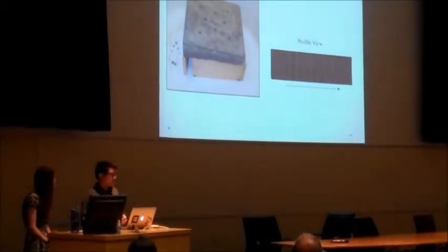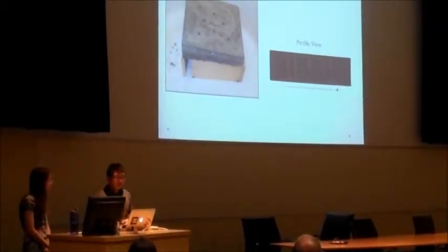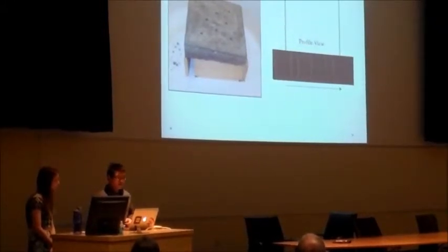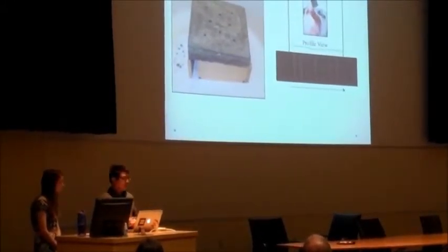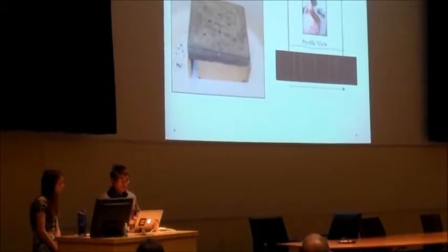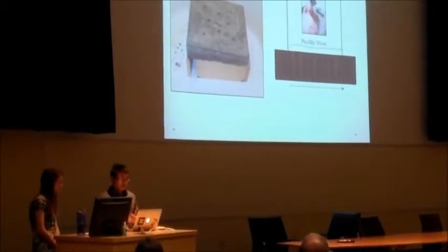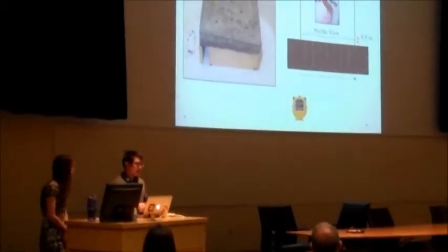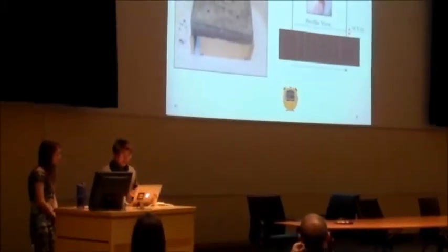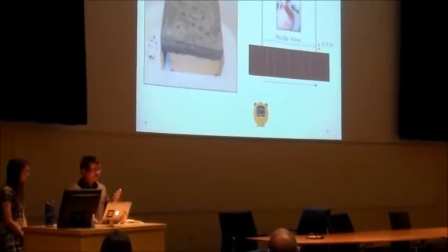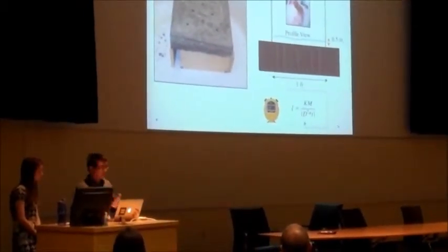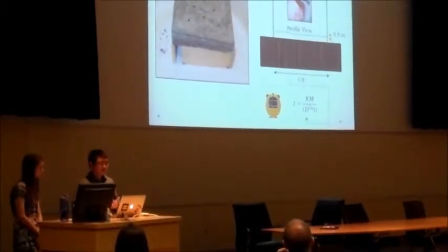And so here's this standard test that we followed, and it involved sealing a collar to the surface of the pavement while pouring water over and trying to avoid leaks, pouring the water at a constant pressure head level while timing, and taking the time that we recorded for this water to drain completely through, plugging it into an equation, and getting the infiltration rate in what's measured as inches per hour.